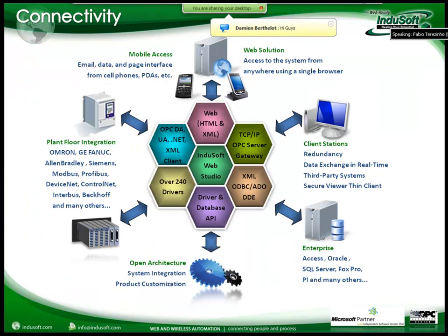Finally, connectivity is a key point for those projects as well. When you install InduSoft Web Studio, more than 240 protocols are readily supported by the software because all the drivers are installed along with the product. Drivers for standard protocols like Modbus RTU and ASCII, Modbus TCP, Modbus Plus, even IEC protocols or DNP for electrical areas, for all the Omron PLCs, Beckhoff, GE Fanuc, Allen Bradley, Siemens. All those drivers are installed along with the product.